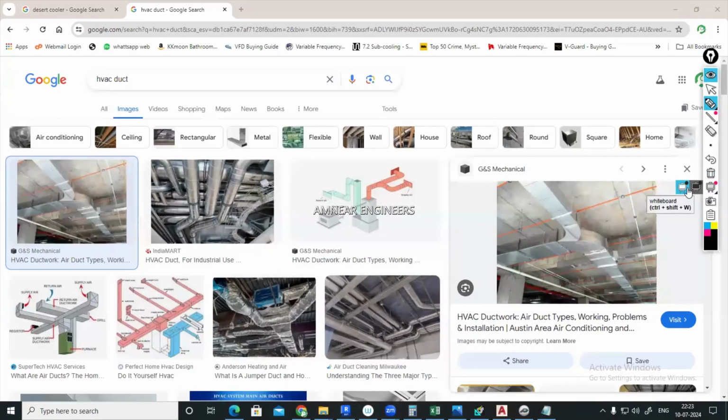That's why when we are doing the duct construction, if the airflow rate is increasing, meaning the quantity of air that we are distributing through the duct, accordingly the dimension of the duct will vary. If more airflow, bigger duct; less airflow, smaller duct. For every dimension, we can't use the same thickness. So with respect to the dimension of duct, what thickness has to be selected? What gauge has to be selected? On what distance we have to provide the support?